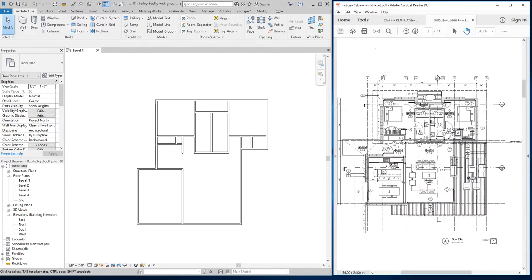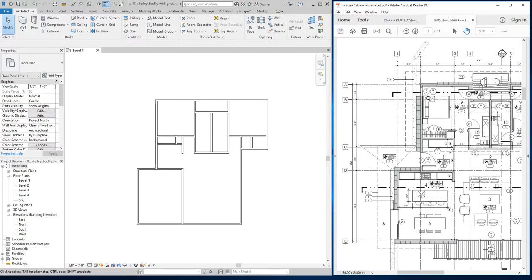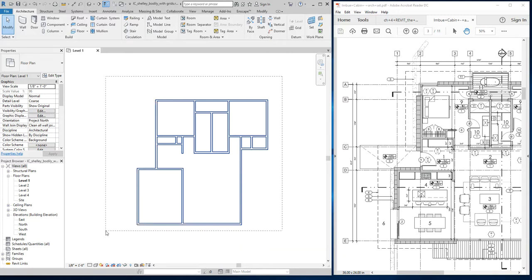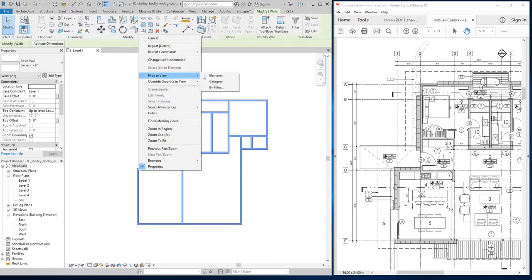And what I'm going to put in its place are some architectural grids here. And I say architectural because I'm setting them. The engineer isn't setting them. Otherwise, you can use the term structural grid. But for the purposes of an architectural set, it's an architectural grid, even though sometimes you'll hear the term structural grid. Okay, so what I'm going to do here is create some grid lines. And I'm going to hide these.